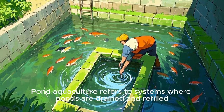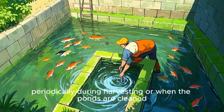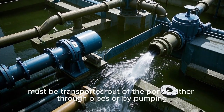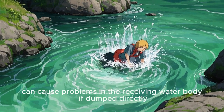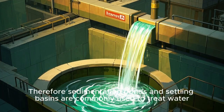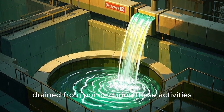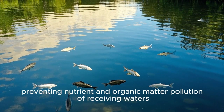Pond aquaculture refers to systems where ponds are drained and refilled periodically during harvesting, or when the ponds are cleaned. During these events, large amounts of water must be transported out of the ponds either through pipes or by pumping. This process can stir up bottom sediments and other solids that can cause problems in the receiving water body if dumped directly. Therefore, sedimentation ponds and settling basins are commonly used to treat water drained from ponds during these activities. They capture solids, preventing nutrient and organic matter pollution of receiving waters.